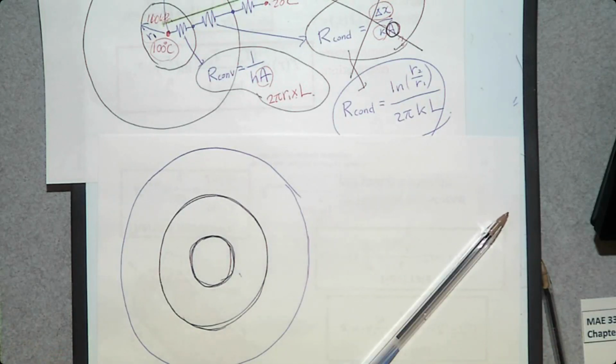When you drive on a highway or anywhere, sometimes when you want to cross a bridge, what does it say on the bridge? Come again? It freezes, right? What exactly does it say? I don't remember. Right. The bridge ices before the road. Why is that? Because the heat transfer from the bridge is much greater than heat transfer from underground.